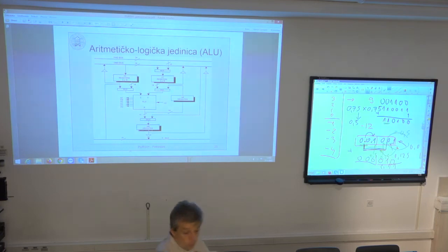Interrupt occurs, you have to do something, you have to use registers, but you don't know what is actually currently in the register, if it is an important value or not, because the main program is using this register as well. On a conventional CPU, you do the context store, which means you push the values from all the registers that you'll be using onto some stack to store them in memory. You use the registers, and then later you pop these values, you restore the values from the stack back to the registers, to what the value originally was before the interrupt was involved.